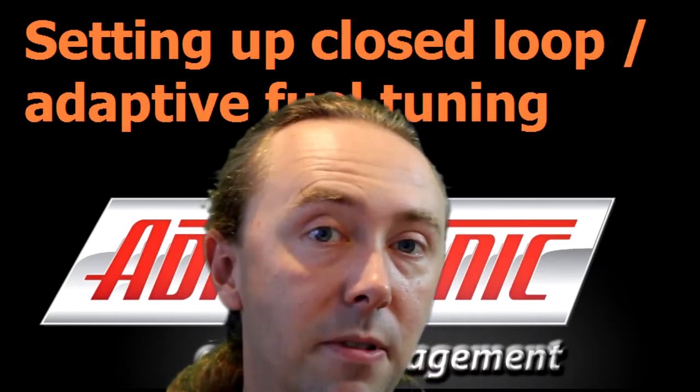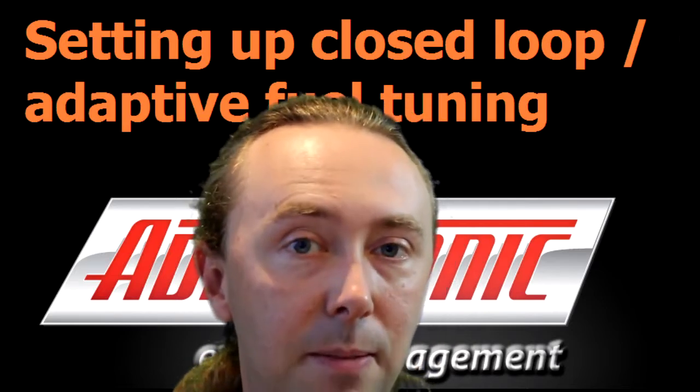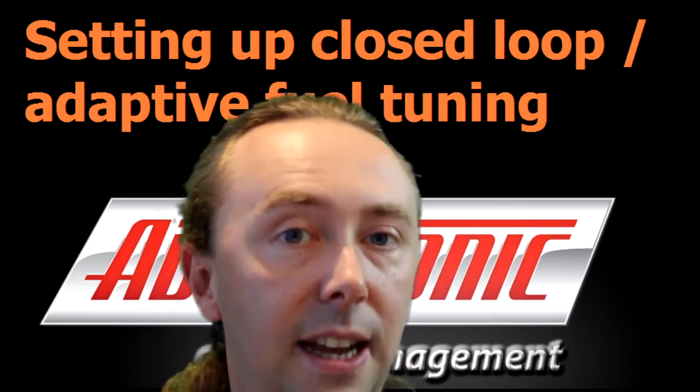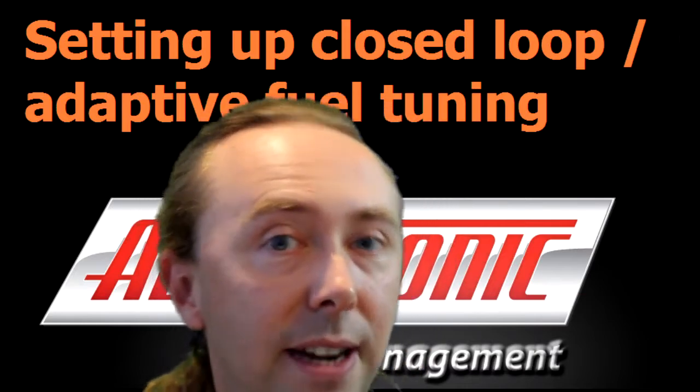The other thing to remember is that the lambda sensor will only read correctly when the engine's running properly. If you get a misfire for whatever reason, then there's a whole lot of oxygen left over in the exhaust, and generally that'll give you a lean reading. Even if it was a rich misfire, you'll get a lean reading because of it.